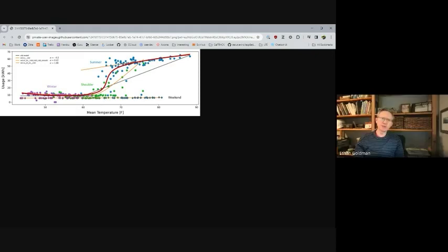Yeah, I mean, unfortunately, the scenario that I'm looking at of the hybrid heat pump systems is even worse than most of the ones that we've talked about so far, which is that it's not just a break in slope, it's an actual discontinuity. So you're going to see the electric demand per day rise as the temperature drops, and then you're going to hit a temperature, and the expectation is that below that temperature, you're going to flatline.